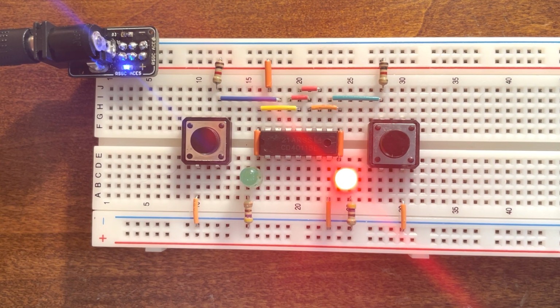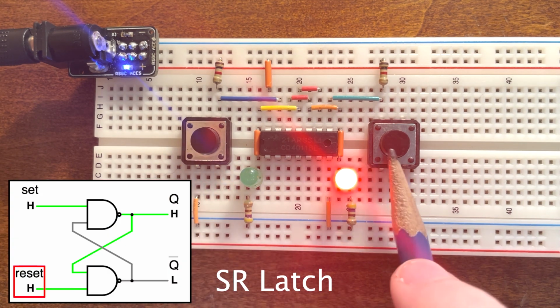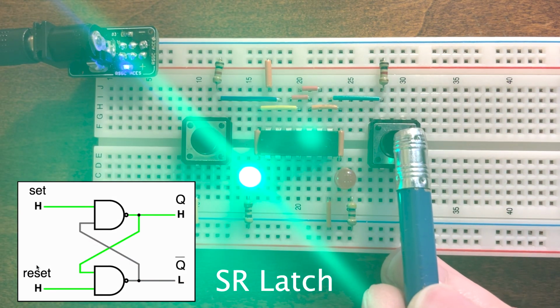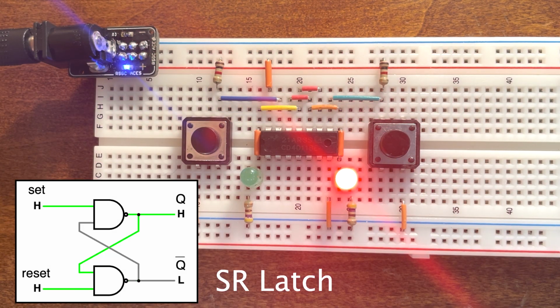This is the most basic type of latch, the SR or set reset latch. It has two active low inputs, set and reset, and two outputs, Q and not Q. It uses NAND gates to create a latch system where the set input presents a 1 on output Q and the reset input resets it to a 0. Not Q, as its name suggests, is always in the opposite state of Q.